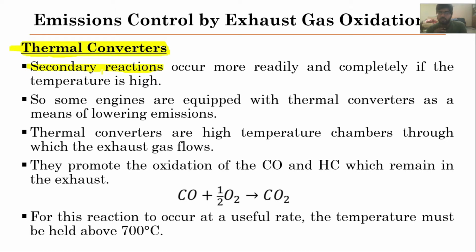So thermal converters are usually employed to enhance these secondary reactions. Means even after the combustion, if there are some undesirable products present in the exhaust gases, they will convert these undesirable exhaust gases into desirable ones, like carbon dioxide and water vapors. Carbon dioxide is not as harmful as carbon monoxide, and water vapors are not harmful as well.